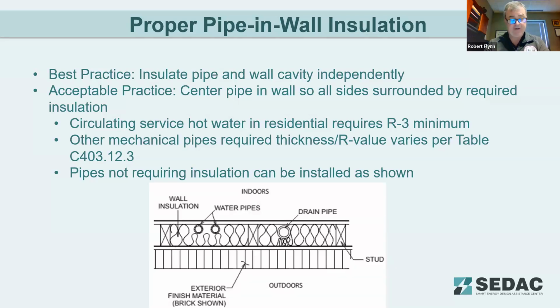They'll actually say we don't need to insulate the pipe in the wall because we're putting batt insulation in the wall that would satisfy the R value needed for the pipe. And yeah, they do put batt insulation in the wall, but like you said, in many cases they'll only insulate one side of the pipe, and the other side is left exposed, whether it be to drywall or just to the open air within that cavity. See it a lot.